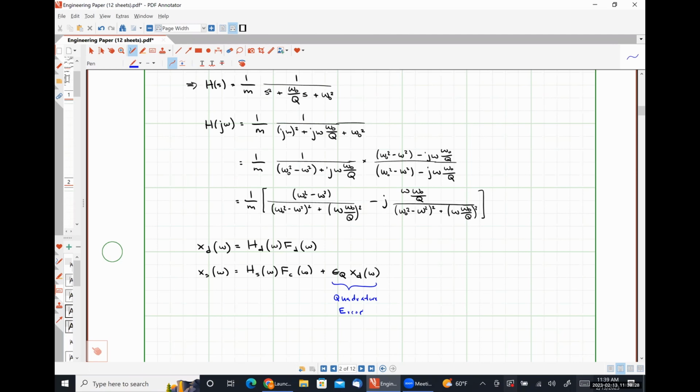We are going to induce a small degree of vibration in that sense mode by exciting our drive mode. And so the quadrature error epsilon Q term represents what fraction of the energy goes into that spurious mode. Okay. So we're taking into account that we may have errors.